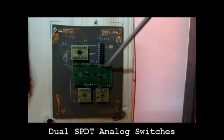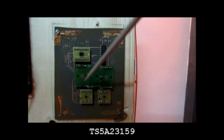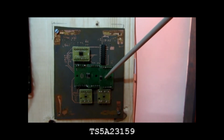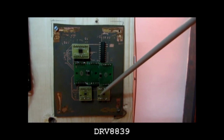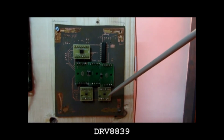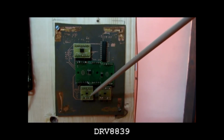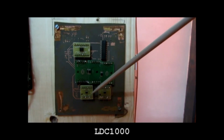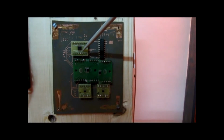They are TS3A24157 and TS5A23159. Motor driver IC DRV8839 is a dual half H-bridge motor driver used to drive the DC motors. Finally, we have the LDC 1000 for inductive sensing, which has an advantage in terms of high resolution in short ranges.